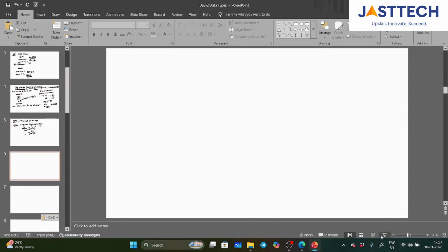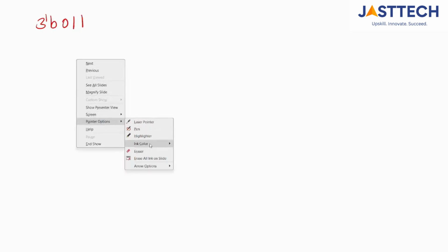If you want to store the value 3'b011, how do we represent it? I am writing this code: module test. I am declaring a reg. How many bits are there? 3 bits are there, no? So the size is 3 bits and this is a binary value. So [2:0]